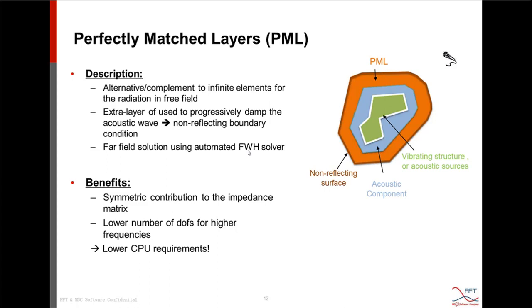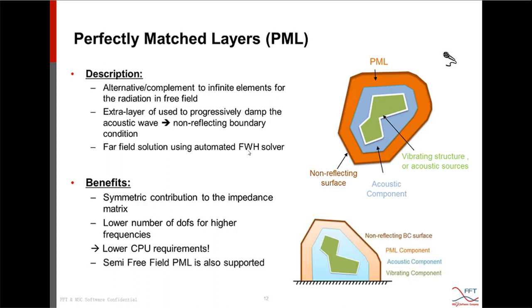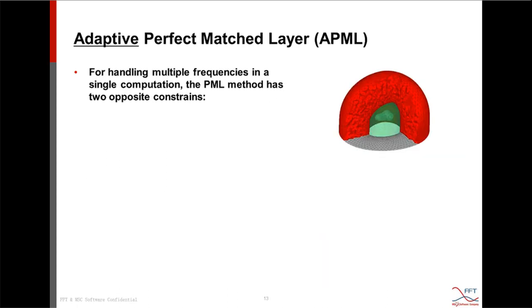Benefit is to allow us to have lower CPU requirement for the same type of problems. And like infinite element method, with PML, we can also analyze acoustic radiation in a semi-free field. So this allows us to simulate an acoustic test, for example, in a semi-anechoic room.